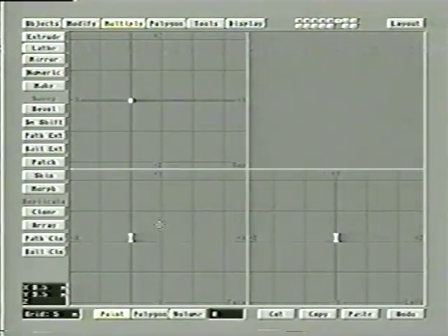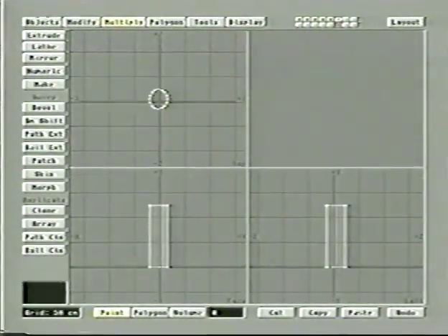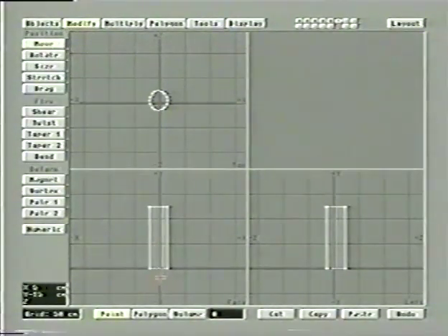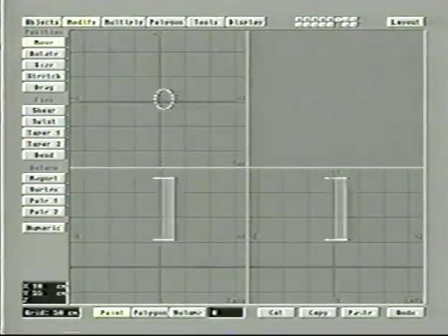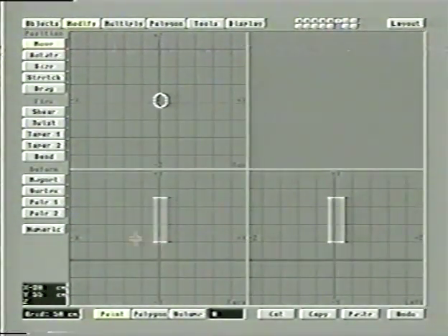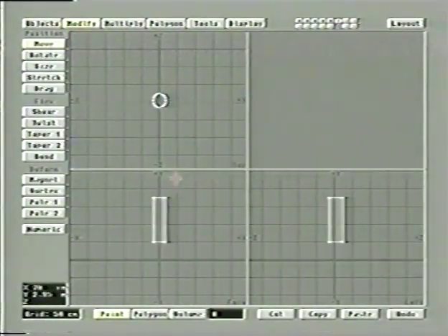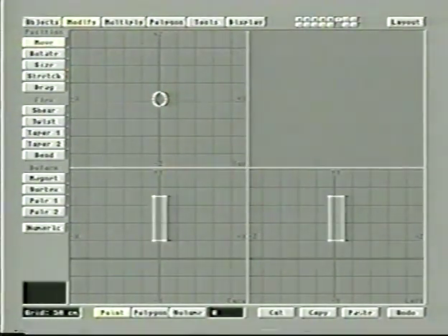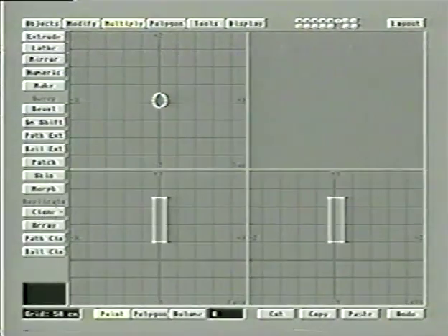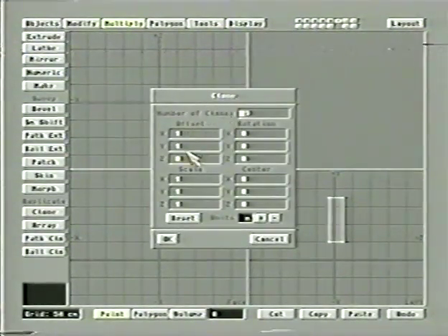We'll undo what we just did. We will take the disc shape here and move it off a little bit. I don't want it exactly on this 0 point. I want it up above somewhat. And let me center it left to right. So to do that, we use x-axis center. So we go to multiply, pick clone. And now what we're going to do here is instead of doing an offset, we'll set these to 0, 0. What we'll do is we will do a rotation.